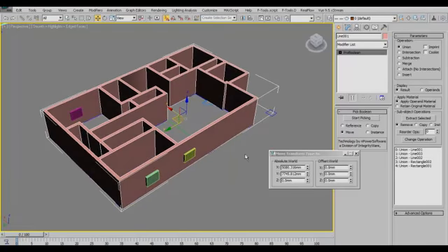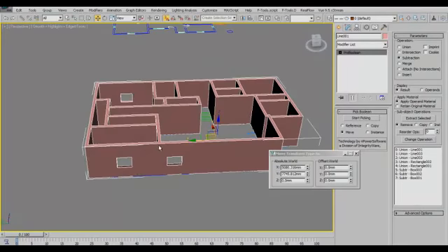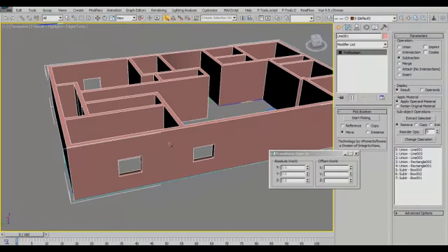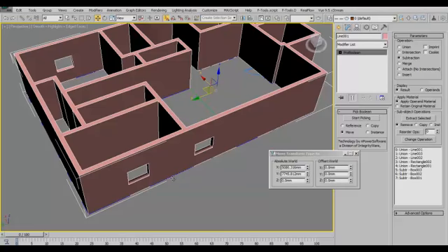So what we'll do now is we want to start booleaning. Now this time we don't want to union these guys, we want to subtract them from the wall. So what we pick is subtract, then we pick start picking, and you can just start picking, and you can see that's cut through that hole.